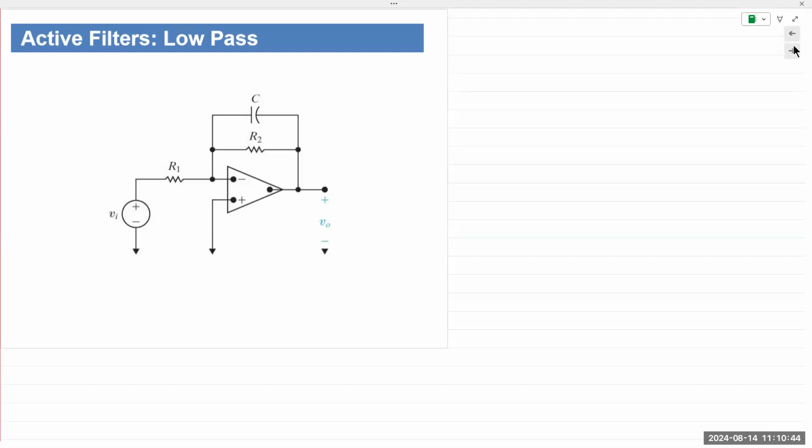Now, if it's a DC applied voltage or current, then the capacitor or inductor would receive the energy and store it and then return it back to the circuit. However, if it's an AC, meaning the input voltage or input current is constantly switching its values, positive, negative, meaning they are a function of time, that means energy is constantly being transferred in and out of these devices. And depending on how fast the changes are taking place, the capacitor and the inductor will oppose that change.